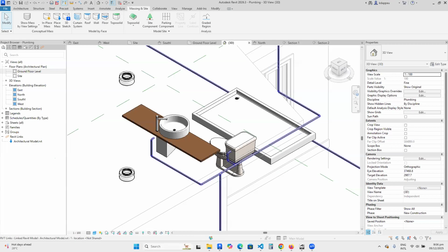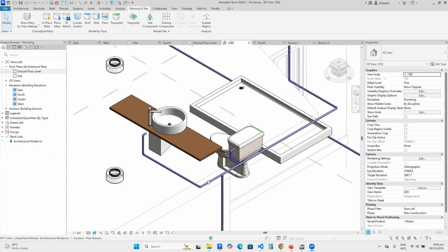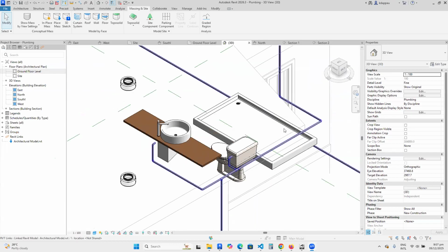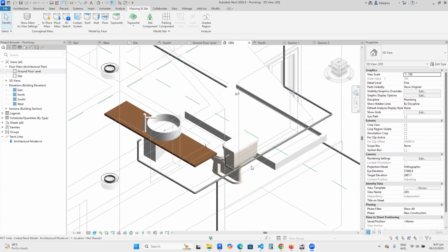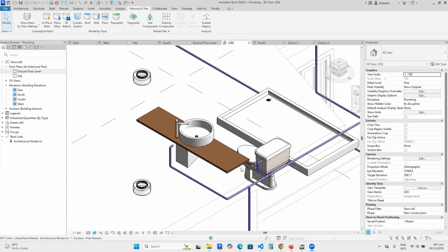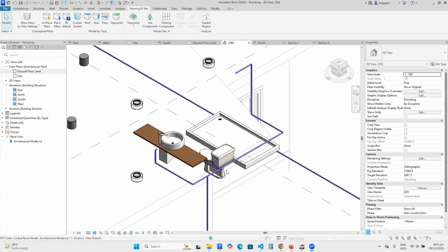Yes, sir. Most of the sanitary appliances, like the wash hand basin and the WC, you have to use a flexible connector. But with the pipes at 25 mm, it's okay for now. It can further reduce to 20 mm. So from where do I reduce it? Is it from this connection or from here or from where?